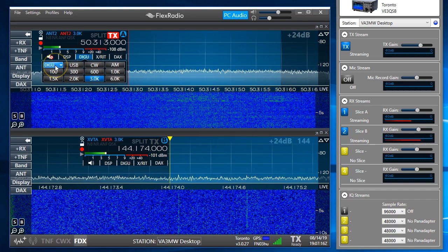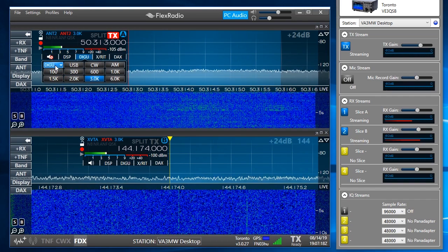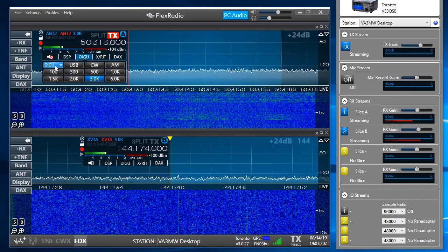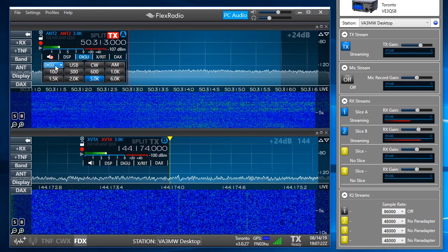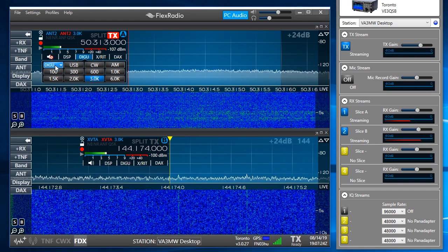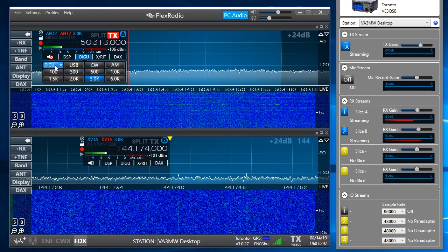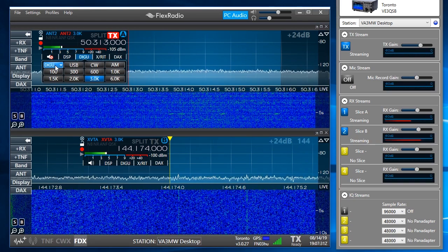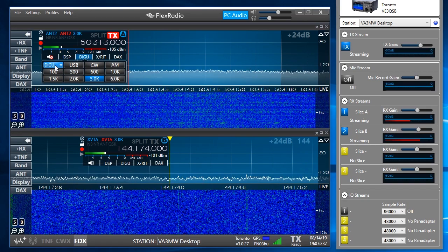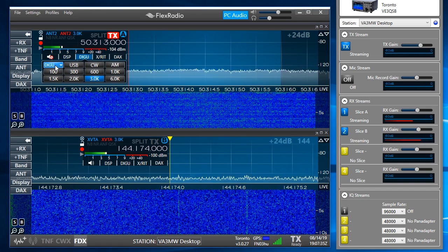The reason we want to use U is that in this format there is no EQ or emphasis or anything between the programs and the radio. It's all, as we call, flat. You don't have to worry about hot spots or sweet spots in the bandpass filters that you do with analog radios. Makes that work fairly well.